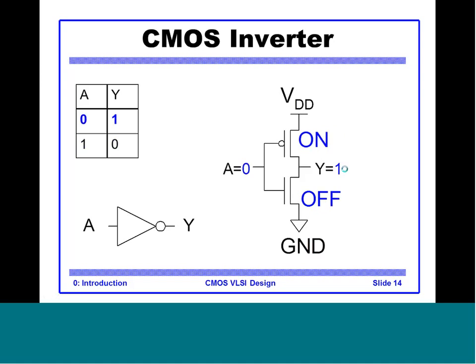Similarly, when A becomes 0, the NMOS switches off, PMOS switches on, and PMOS switching on pulls Y to 1 or Y to VDD. So that is why PMOS is also called a pull up device.